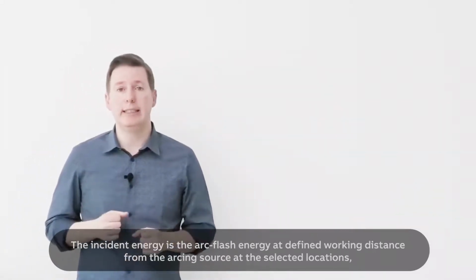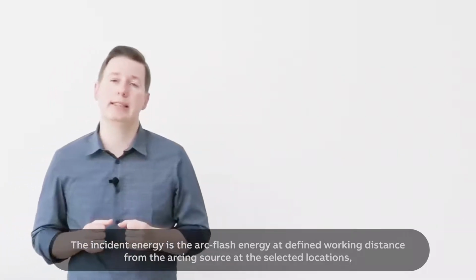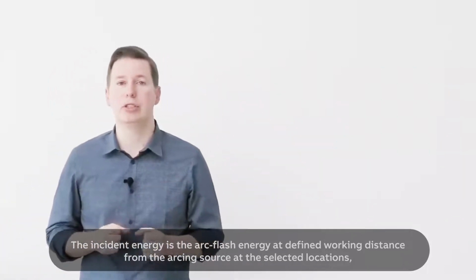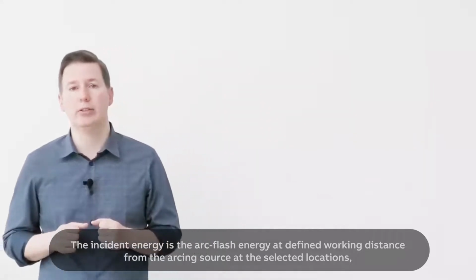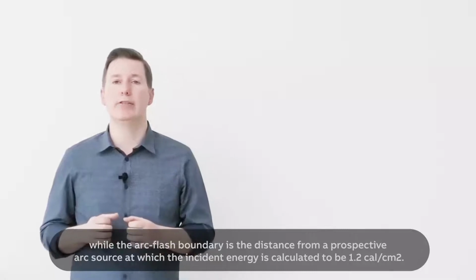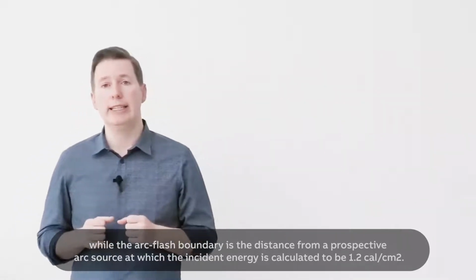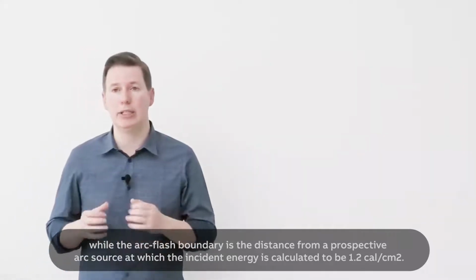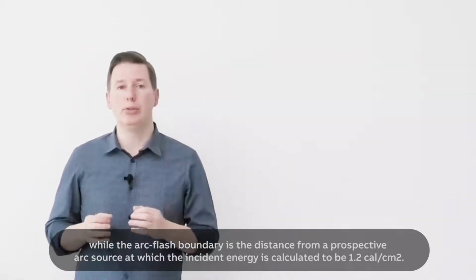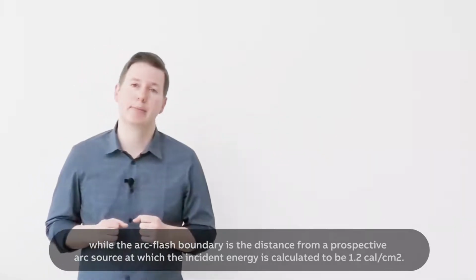The incident energy is the arc flash energy at a defined working distance from the arcing source at the selected locations, while the arc flash boundary is the distance from a prospective arc source at which the incident energy is calculated to be 1.2 calories per square centimeter.